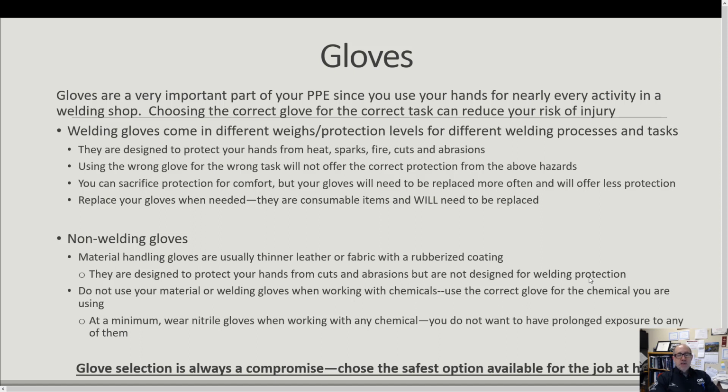So, non-welding gloves. Material handling gloves are usually thinner leather or fabric. When I was younger, we all had these leather driver gloves. Anymore, you're seeing more of the synthetic rubberized gloves, which I actually prefer for most material handling, because they're more cut resistant. You get better feel with them, and you actually get some traction on stuff. Just don't weld in them, because they'll melt right to your hands.